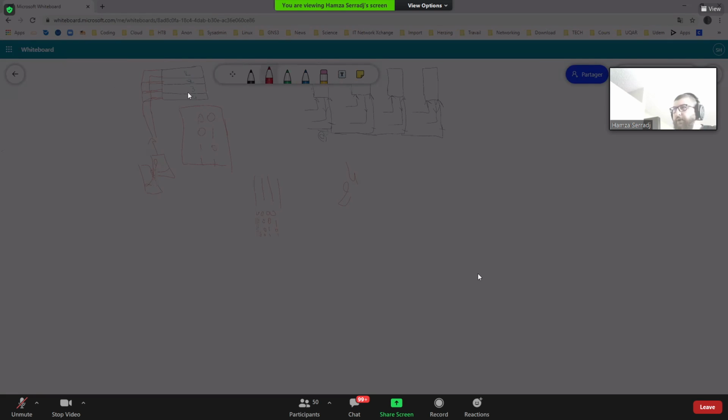So having 4 locations, I'm looking for just 4 addresses here. I can do them with 2 bits, 2 wires. I have the possibilities 0 0, 0 1, 1 0, 1 1. It's done. I have the four addresses here. So this one will be 0 0, this one will be 0 1, this one will be 1 0, and this one will be 1 1. And it's done. Right? So I can now map a memory bank of 4 locations, of 4 addresses, using 2 wires. Now let's go back to our example here.